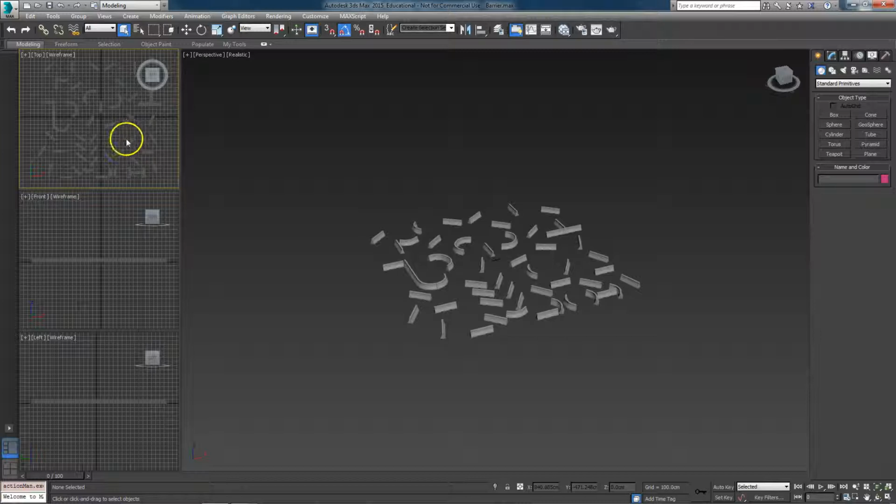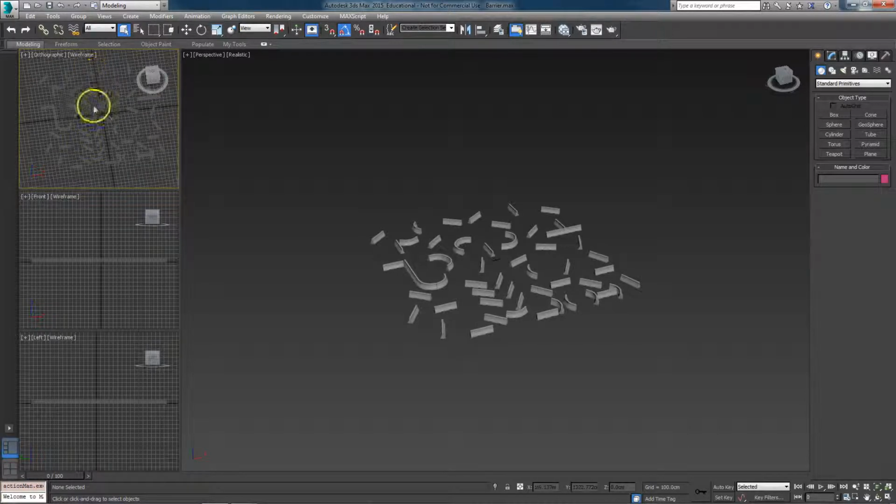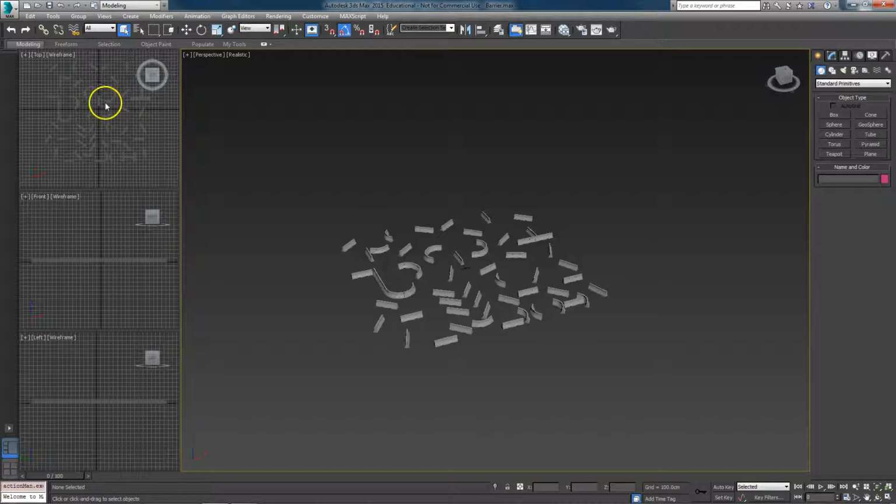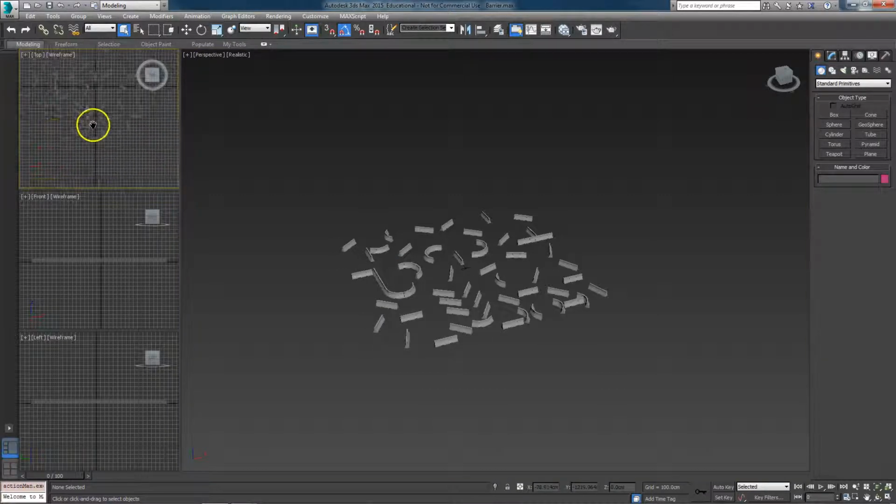Another thing you have to be concerned with is if I hold Alt and then try to rotate, that window is no longer a 2D window. Before it was top, now it's orthographic. And with orthographic, you can see you lose a lot of that 2D fundamentals behind it. So to convert it back to the top, you hit T on your keyboard, and that will reproduce it.